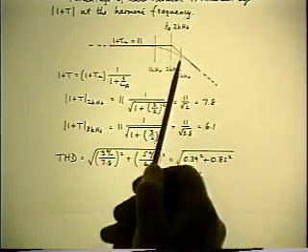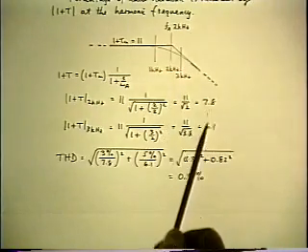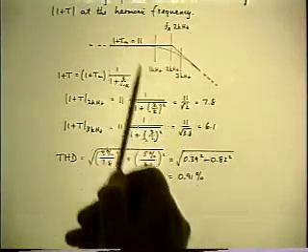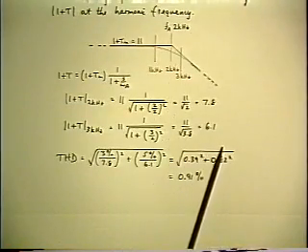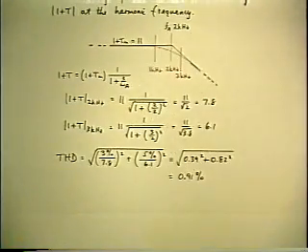In other words, the reduction factor for the third harmonic is already little more than half what it was at mid-band, at 3 kilohertz, because the loop gain is dropping off well within the flat bandwidth of the overall voltage gain.